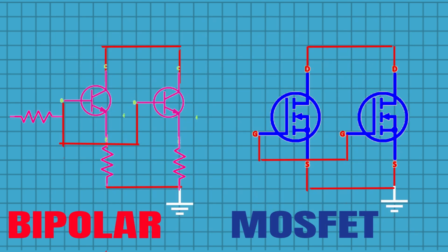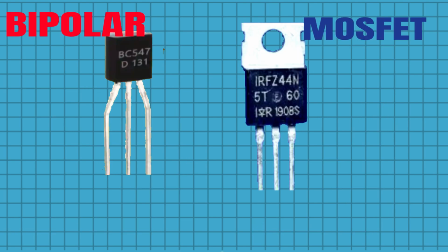But when it comes to powering these transistors, a MOSFET requires no ballast resistor, but the bipolar does require a ballast resistor. Because the bipolar, if powered without the resistor, would give more and more of the shared current to the hottest transistor, as it would be getting little or no help from the partner, and would burn out. This is because the bipolar responds to temperature: the hotter it gets, the more current it wants to pass to its leads, which leads to current hogging. BJTs are workaholics, while MOSFETs tend to slack off.